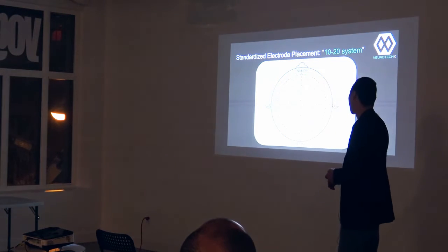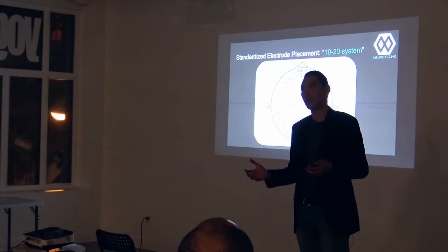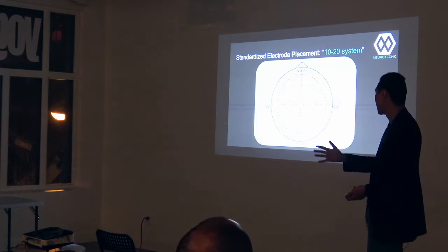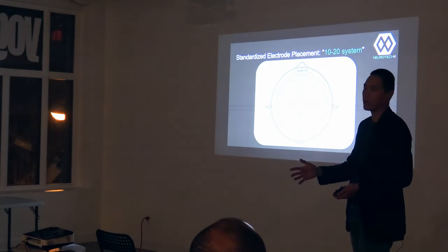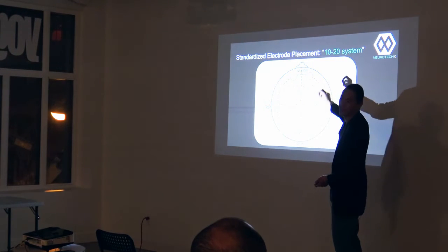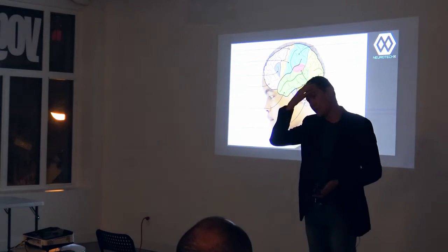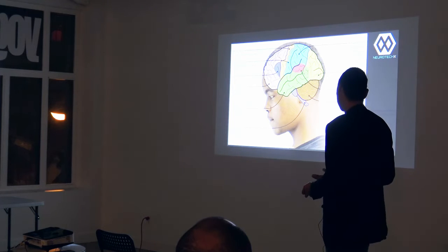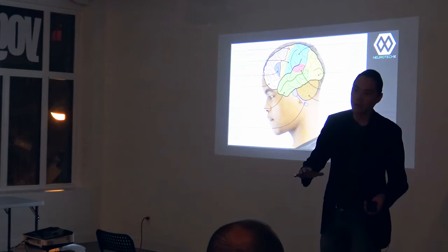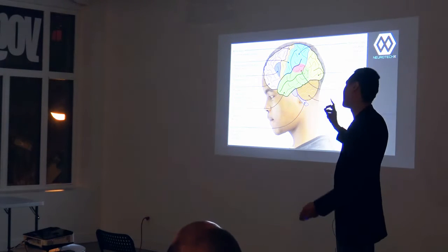So for the base of these presentations, there are different types of electrode placement systems, but right now we are concerned with the 10-20 system. This is what I would say is the most accepted standard for electrode placement. Even though it's a really young field, there are practices that go back for decades, and this is one of them. It means essentially where you place the electrodes, and it depends on where you place them at different points of interest. If you want to see how someone is performing as they do a lot of math, they're going to need a lot of prefrontal cortex activity, versus someone doing something that requires a lot of motor activity or language. So depending on the experiment you're running, you need to recognize that what you're trying to scan out of the brain depends on where you put the electrodes for best placement and what type of hardware you get. That's pretty key.